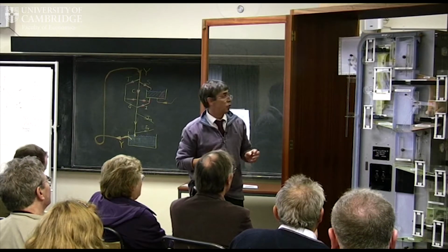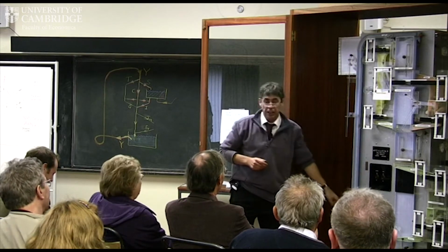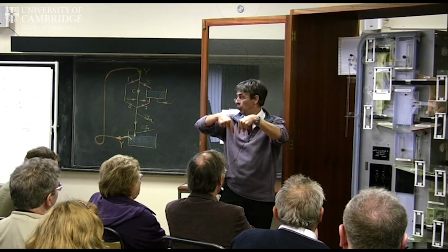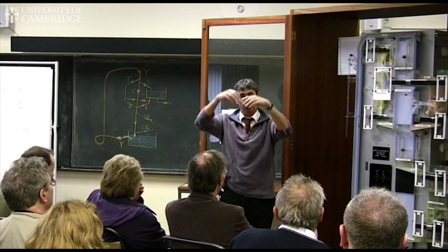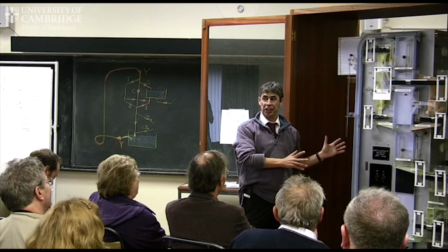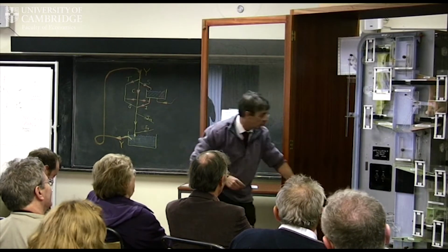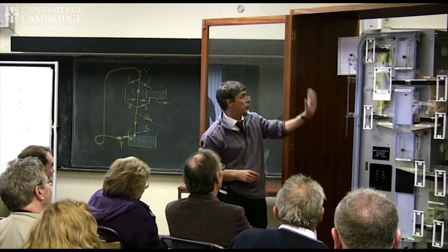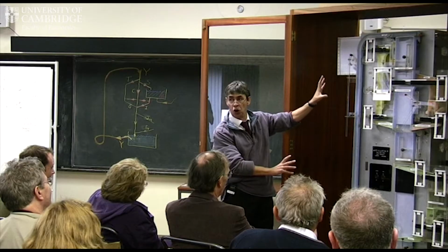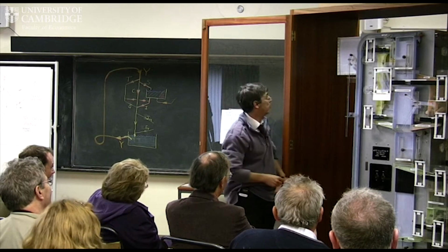The first thing we had to do, you may notice, are these danger 240 volts stickers on it here. There are certain water level detectors in here. It used to be 240 volts straight into water. It used to go boof, boof, boof to detect the water level with steam coming off. And you can't run it under today's health and safety legislation. So we had to step that down to 20 volts. So that was the first thing we did. So now we can run it. But apart from that, we haven't made any intervention in it at all, other than just connect all the pieces the right way again.